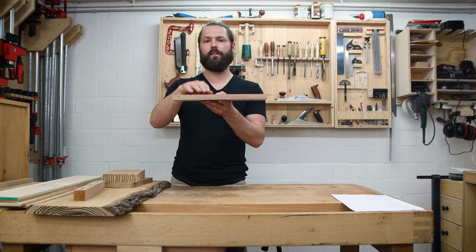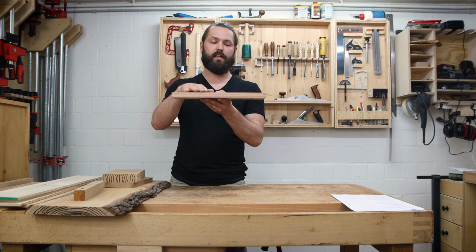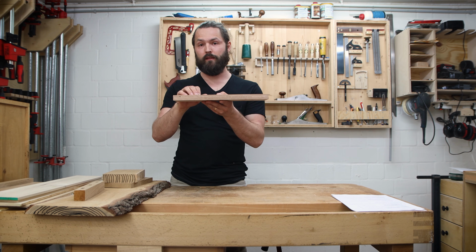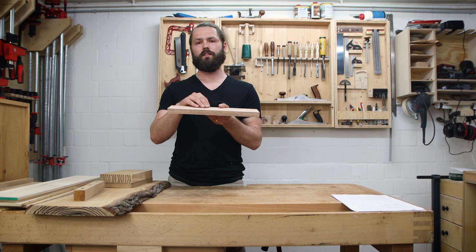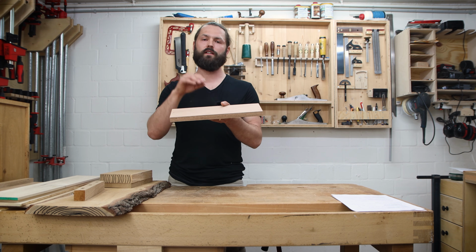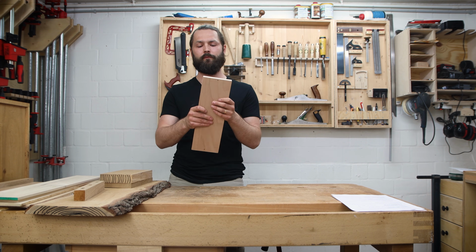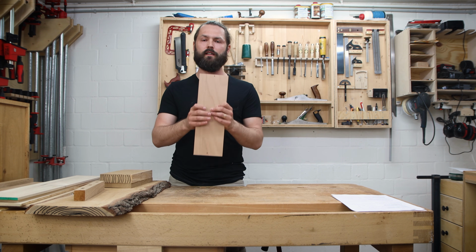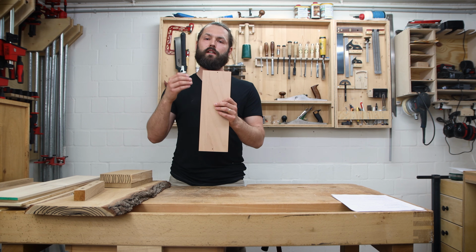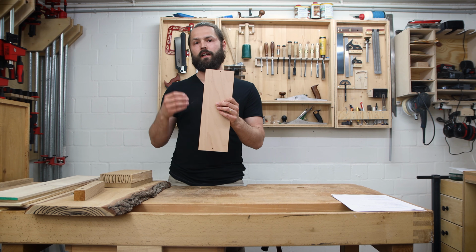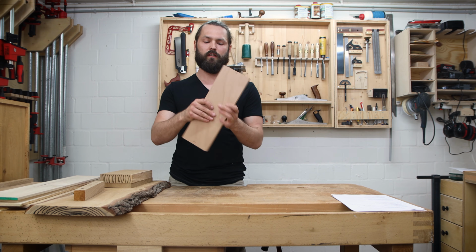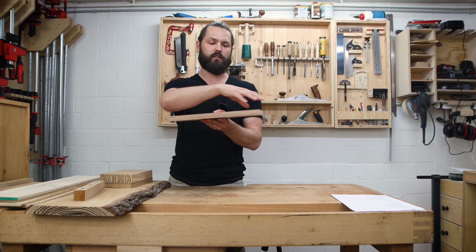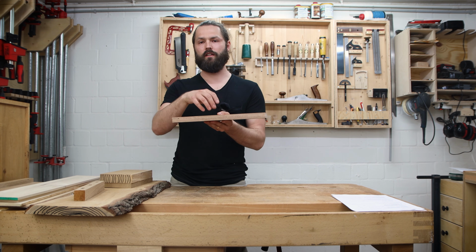By gluing them together in this panel, you get a pretty stable panel that does move a little bit in each direction, but not too much. In the construction with plywood and furniture projects, you don't have to worry about wood movement. If you need a fairly stable panel, you can use plywood. You can use plywood, for example, for the back of your cabinets or also for drawer bottoms. And it makes a great drawer bottom because it does not expand and contract much in each direction.